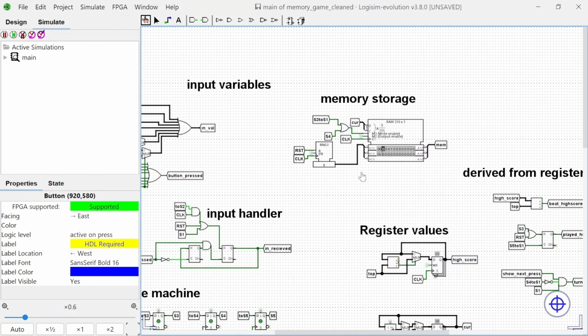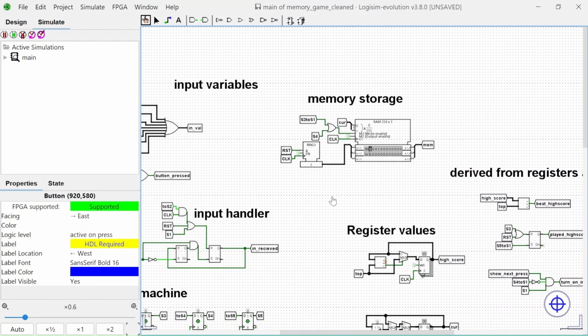Mem was implemented using the provided Logisim RAM module. Random numbers are also generated from a provided Logisim module. The 3-bit random number generator always feeds into the memory's input, and memory in RAM will only be accessed by the address cur, and the output will always be enabled.